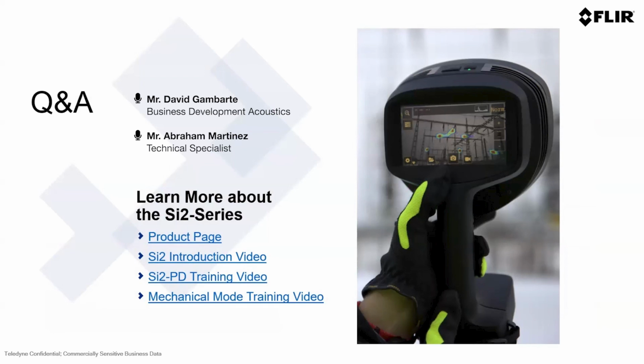I'm not aware of thermal use for that. But as we always say, thermal and acoustic imaging are complementary. They are really powerful tools together. In some cases, you might find a partial discharge that does not yet represent a change of temperature, and you will already know there's something going on, maybe harmless or maybe important, depending on the type of component and the type of partial discharge. In other cases, you might find a variation of temperature that represents a problem, in combination with partial discharges or without them, because they are not happening there for different reasons. These tools work in combination, and we would like to highlight that the recommendation is to use both thermal imaging and acoustic imaging.